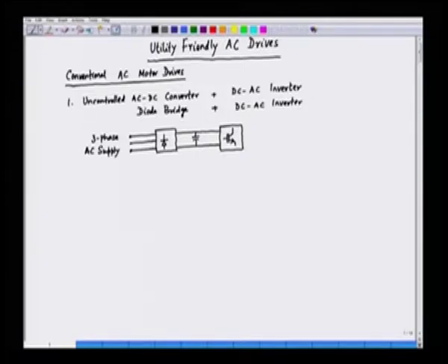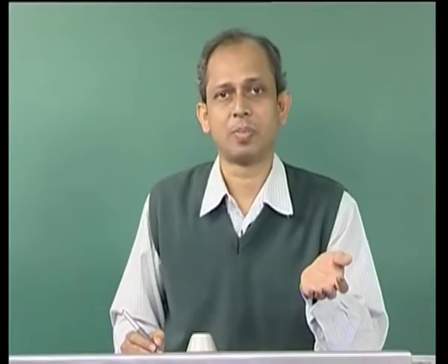When we have a low power application, say for example below 10 kilowatt, we can go for a single phase bridge.